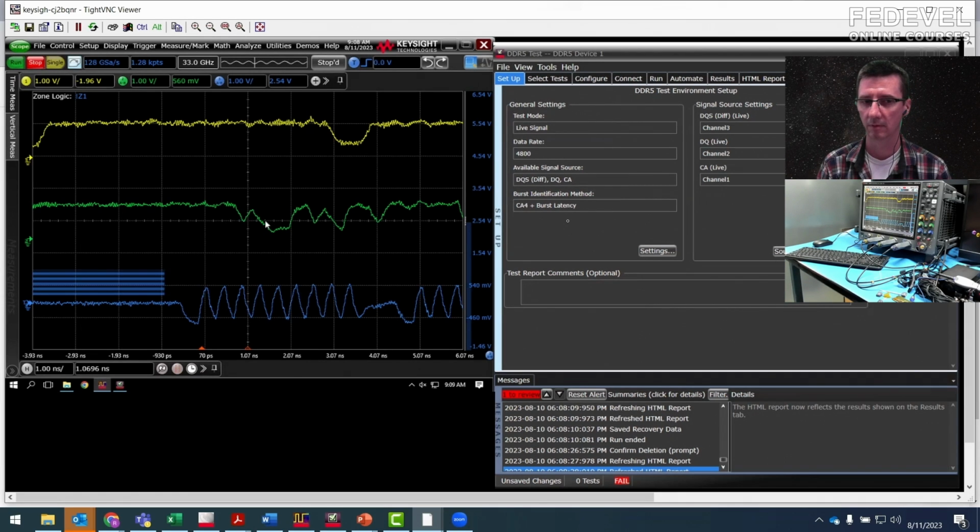If we have access to the mode register settings, we can query or read the final training settings that were applied. And if we can get the DFE tap values from the software training sequence, then you can put it into our system. Exactly. Yeah, a lot of people do that.